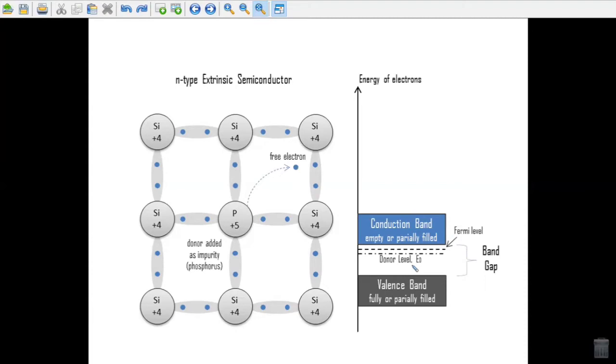The remaining positive charge, or a hole, is localized on the immobile arsenic atom and does not take part in the electrical conductivity. The impurities which supply electrons without simultaneously creating holes are termed as donors and the corresponding energy level as donor levels. The semiconductors doped with donor impurities are known as N-type semiconductors. Since the conduction in this case is predominantly due to electrons in the conduction band, they are called majority carriers, and the holes in the valence band become minority carriers.